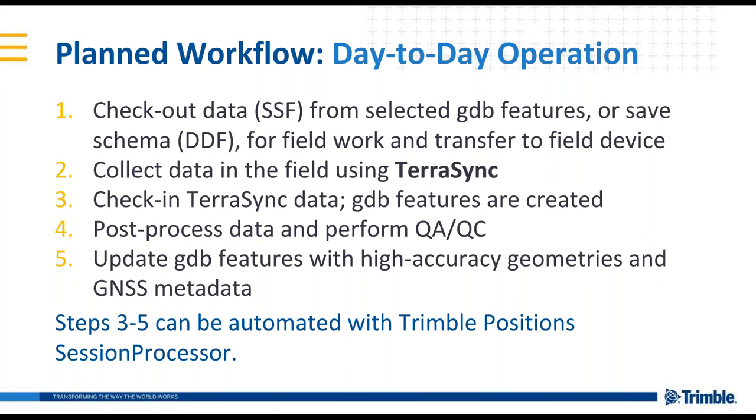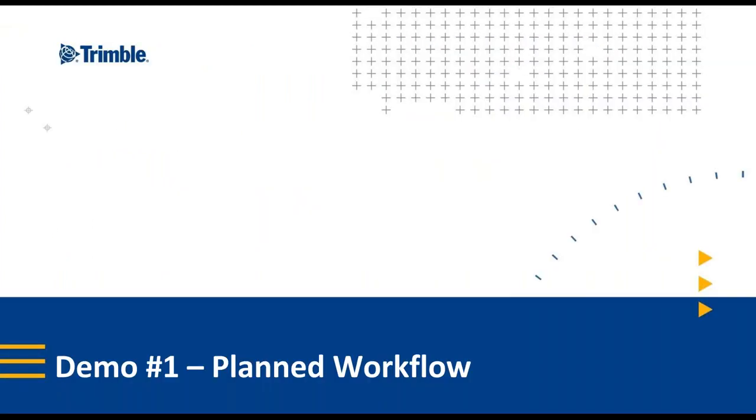I did want to put in here at the bottom where it says steps 3 through 5 can be automated with Trimble Positions Session Processor. The Session Processor is a tool that we came out with a couple years ago for headless processing of sessions on a server machine or some other sort of non-UI machine. It does require a license of ArcGIS Desktop, but what it can do is watch certain folders. You configure it and say, I want to watch this folder, and anytime an SSF gets dropped in there, I want to process it using these settings. I want to post-process it. I want to automatically update feature geometries, etc. So that's what Session Processor is.